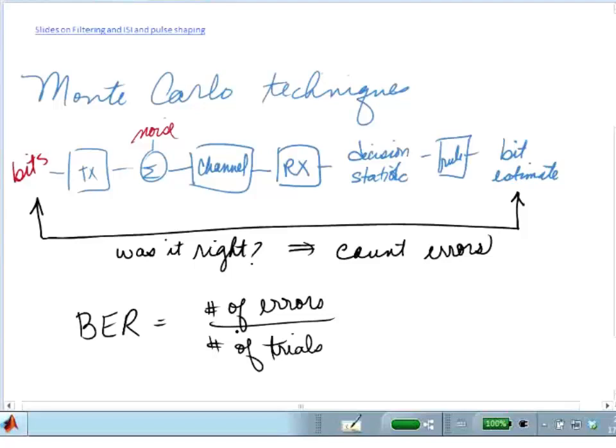So I can use this approach in any numerical simulator, be it MATLAB or OptiSystem, to help me estimate the bit error rate whenever I'm using a system which is non-ideal in some way, where my analytical equations are no longer valid. Sometimes it's just impossible to come up with closed-form solutions in these situations. In this way, the numerical simulator is really the only way we have, short of going into the laboratory, to find out what's going on.